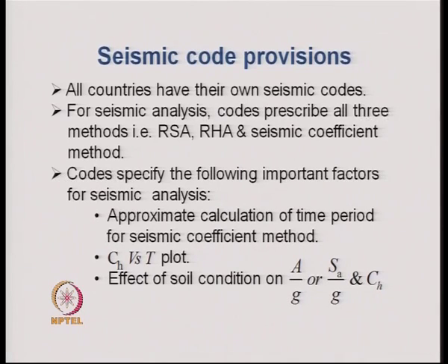It could be a time history of ground motion which has developed the maximum amount of damage in the past in that particular region, or one can construct a time history of ground motion for a given response spectrum or a given power spectral density function of response.